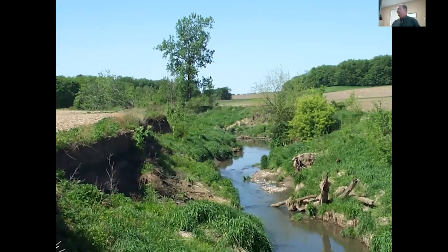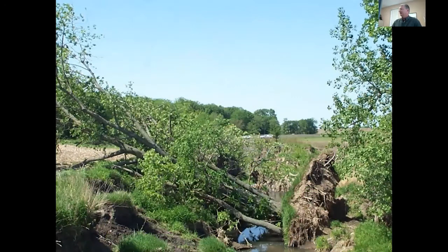So you can have channels that look pretty rough, and they don't get stabilized until they're done down cutting and done widening without intervention. So that can lead to those kinds of tree issues that you see on the bank. Maybe someone thinks it's just a velocity problem against the bank that's causing this tree to get undercut and erode, but it could have started as an issue with the bed of the channel and some re-meandering that the channel's trying to do, and it may have just undercut this tree and allowed it to fall in.